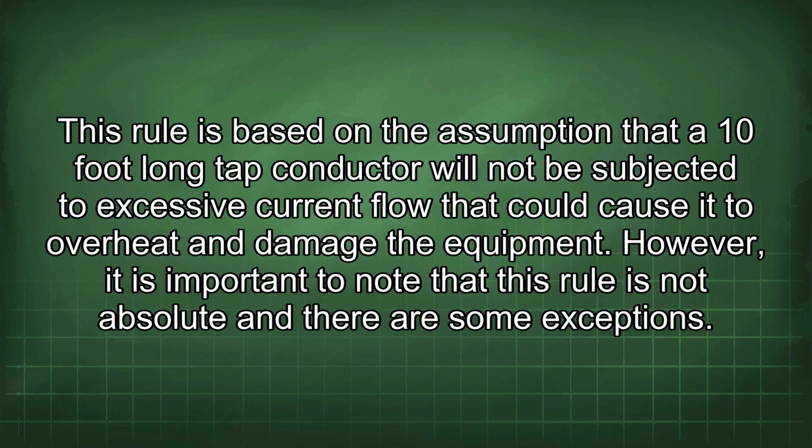This rule is based on the assumption that a 10-foot-long tap conductor will not be subjected to excessive current flow that could cause it to overheat and damage the equipment. However, it is important to note that this rule is not absolute and there are some exceptions.